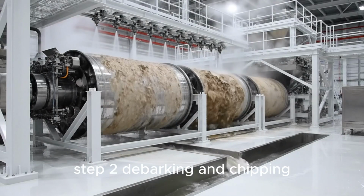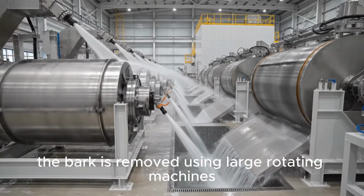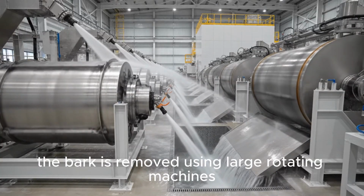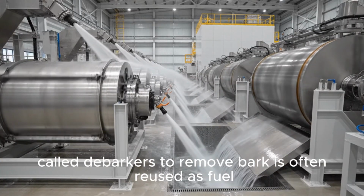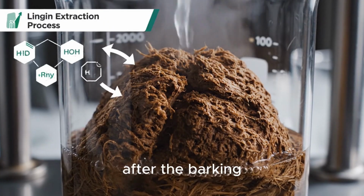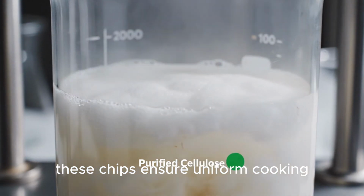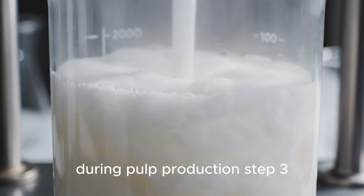Step 2. Debarking and chipping. Once logs reach the paper mill, the bark is removed using large rotating machines called debarkers. The removed bark is often reused as fuel for burners. After debarking, logs are cut into small pieces called chips. These chips ensure uniform cooking during pulp production.